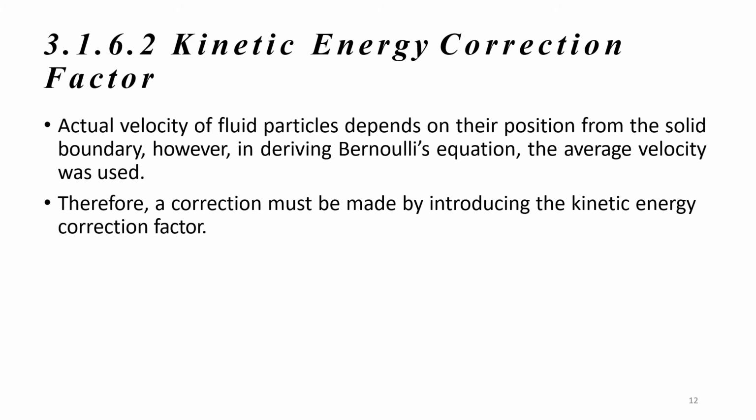Okay, then kinetic energy correction factor. Okay, actual velocity of fluid particles depends on their position from the solid boundary. However, when we derive the Bernoulli equation, we are using the average velocity. Therefore, a correction must be made by introducing the kinetic energy correction factor.